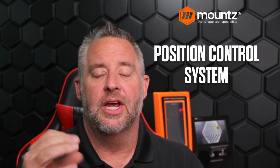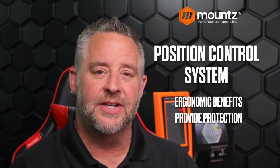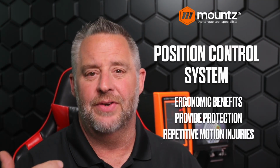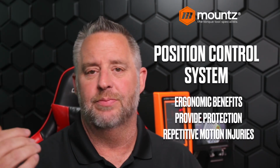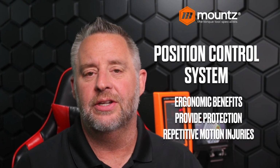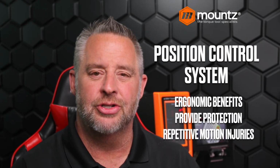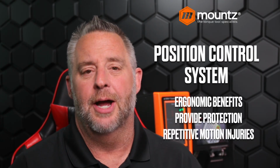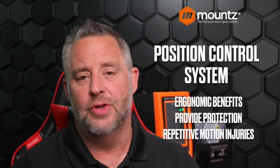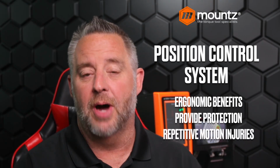Now, the control system itself is also going to provide ergonomic benefits because the tool is secure in a torque arm. And so if you have torque values that are above, say, 15 to 20 inch-pounds and higher, you'd want to secure that tool in a torque arm to help prevent any type of repetitive motion injury or any type of carpal tunnel, things like that for the operator, because trying to do that over long periods of time can introduce those types of stresses to the body.